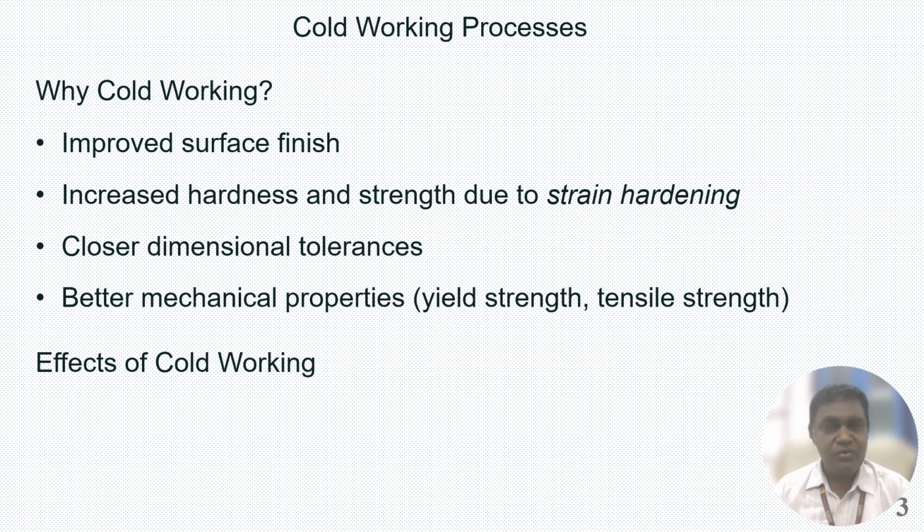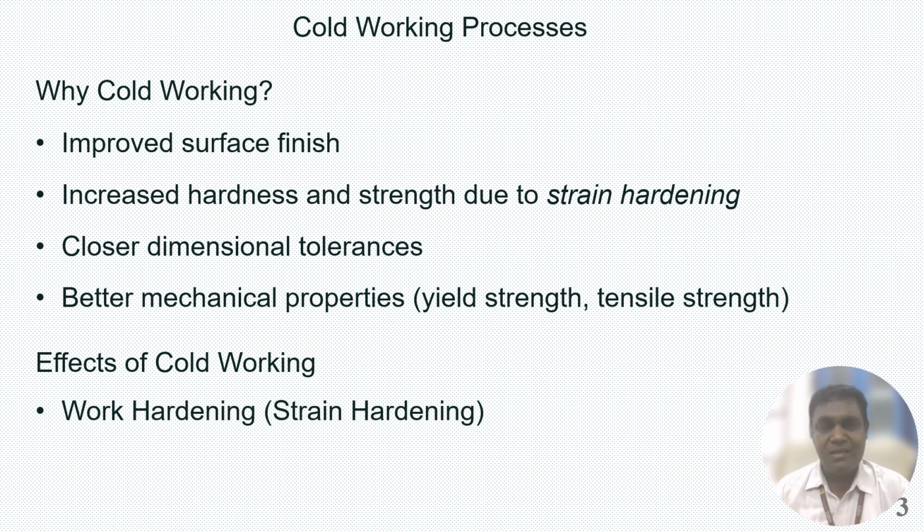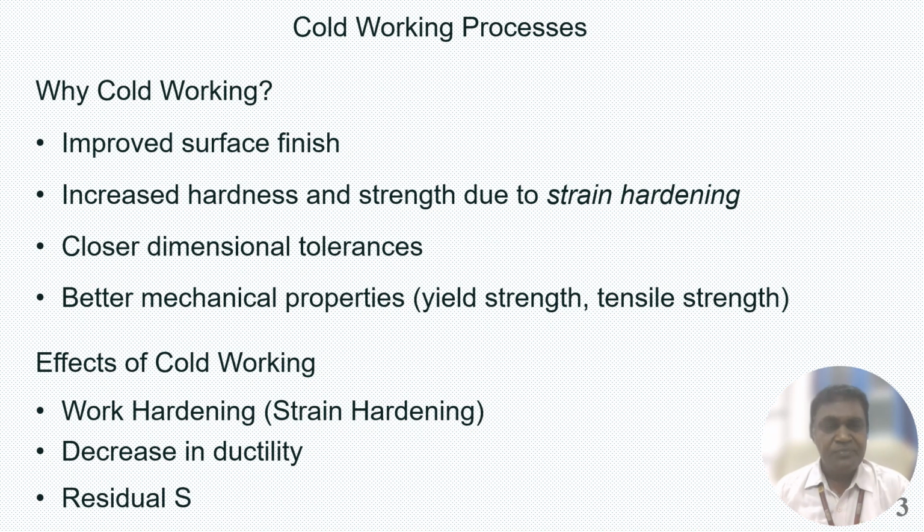So, the effects of cold working. The main effect of cold working is work hardening, that is strain hardening, and a decrease in ductility, and residual stresses increase. These are the main effects of cold working: one is work hardening and decrease in ductility, and residual stresses are possible.